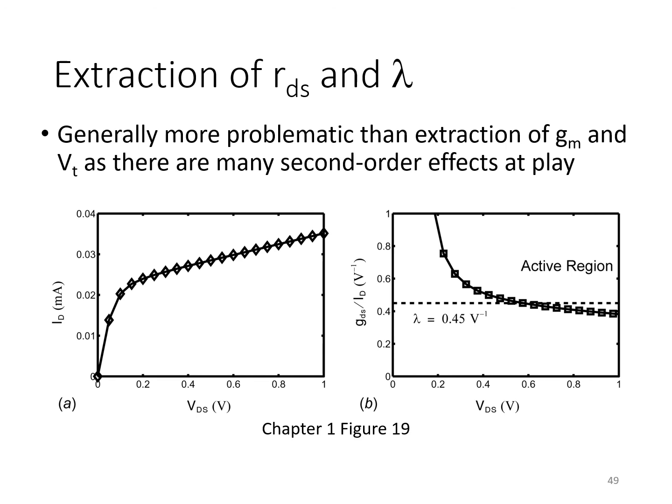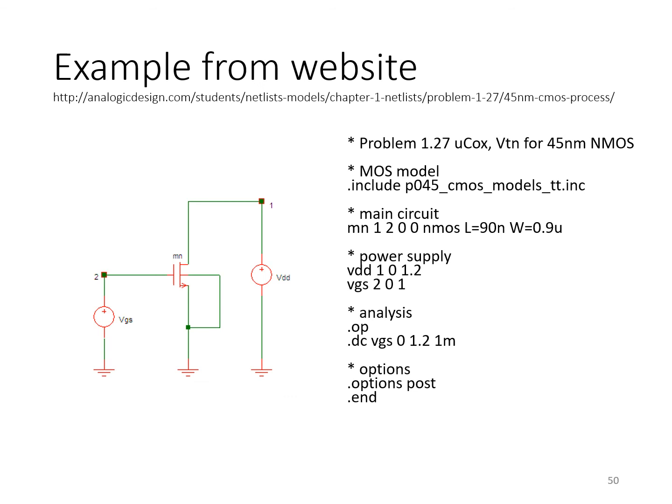And again, this is meant to provide you with an approximate transistor model that's useful just for first pass design. You're not going to use these model parameters to calculate accurate values such as power consumption or gain of a circuit. You're going to rely on SPICE simulations to tell you that. And so here's some more detailed analysis and a link to netlist examples of how these sweeps can be done.